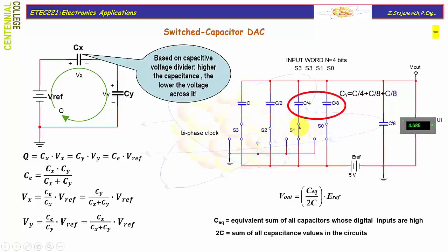For instance, if S1 and S0 are left connected to ground, they will be in parallel and will also include in parallel this matching capacitor. Basically, the overall result will be a series circuit shown to the left, where Cx represents the total capacitance of all branches with logical 1, in series with the total capacitance Cy of all branches with logical 0.